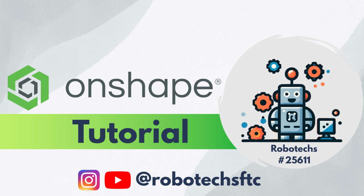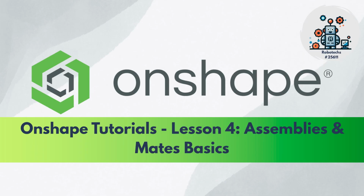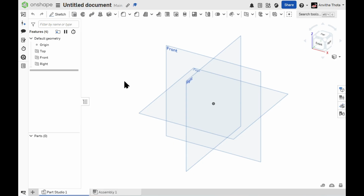My name is Anvita and I'm the lead of the design team on our team. Today we're going to learn how to create two parts in Onshape. Specifically, we'll make two simple shapes, a cube and a triangular prism, and then we'll connect them together by using mates in an assembly. By the end of this video, you'll understand how basic parts are created and how they'll interact with each other. To make the cube, first make a part studio.